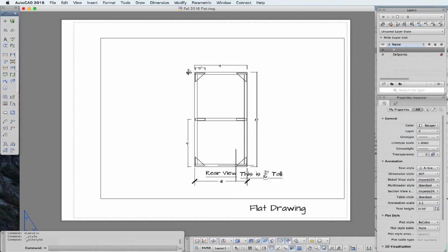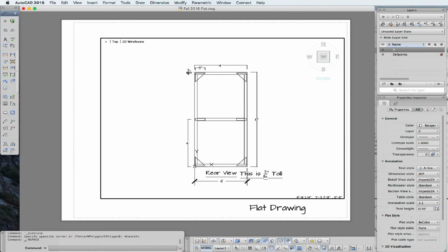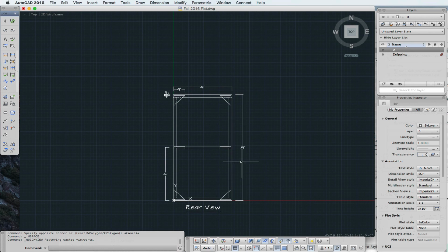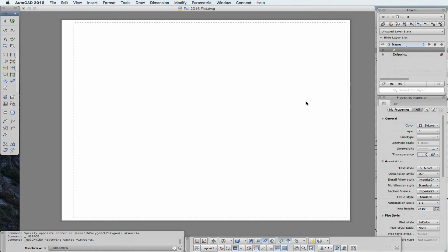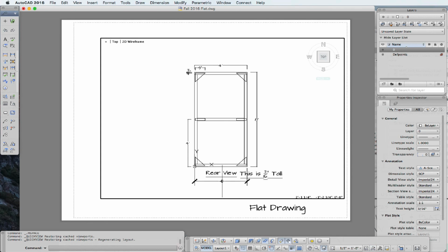Now why don't we just do all the dimensions in this mode? Well, this is why. I'll show you. If we double click on the drawing, it takes us into model space temporarily, and we can do our navigation. When I change our view, all the dimensions that are built into the model space that we were using before, these dimensions here, notice it's missing that new one that's at the bottom, these dimensions here will stay accurate. And this dimension that we've just added will not. Watch this.